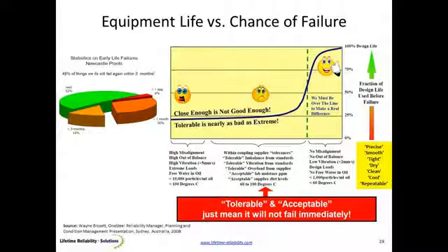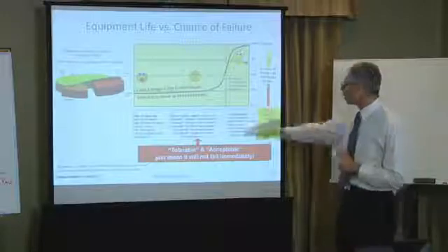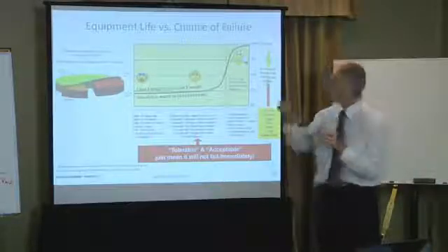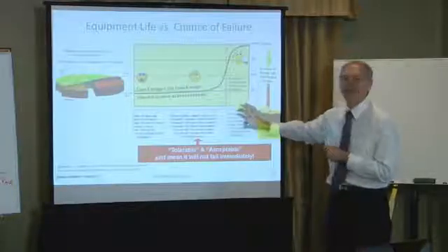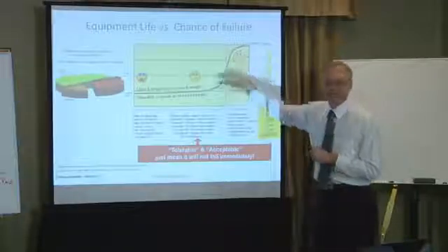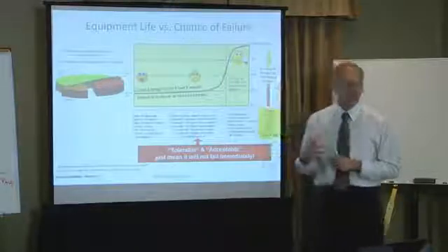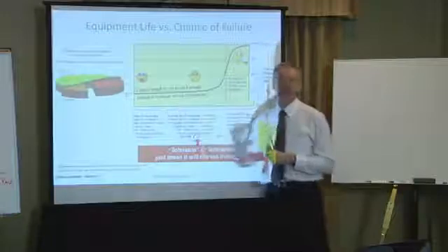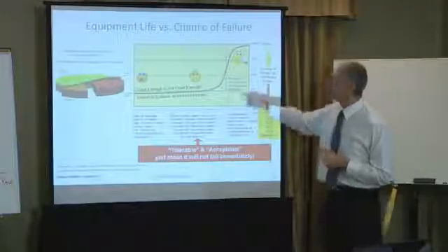It isn't until we cross that boundary and there is no misalignment, there is no out of balance, the total vibration is very low, the design loads are what they should be and where they should be, the oil and lubricant is in very good condition, the temperatures are controlled, so the interference fit of parts are as they should be in that 10 micron zone. Once we cross that boundary and we control the world our parts live in, our reliability jumps up to the full design. It's not a gradual jump, it's a step change. Massive step change. But we have to be in that zone. Nothing else but being in that zone gives us the reliability that we're after. Anything on that side, we never get the uptime, the low costs that are possible with high reliability. High reliability is this zone here.